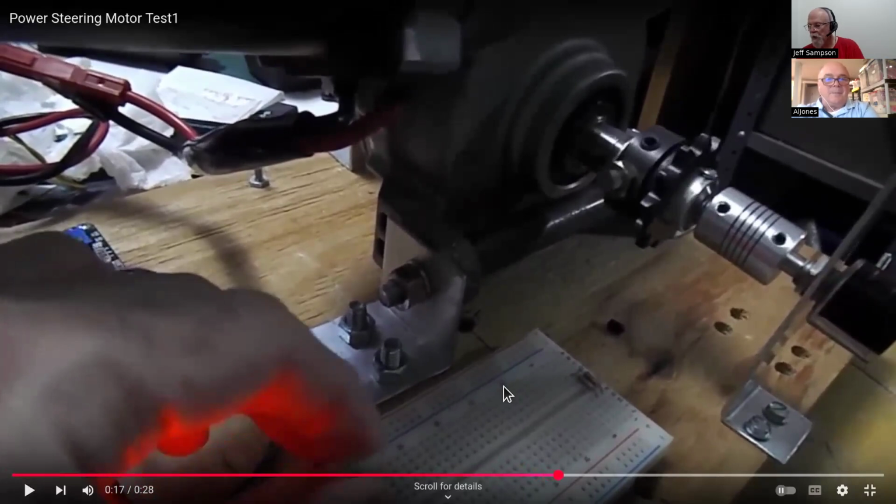And the reason why it stops squealing when the motor comes to a stop is because when the 2 pots are equal, it just does not send out a PWM. So it's not controlling the motor at that point. So that's why it's doing that.